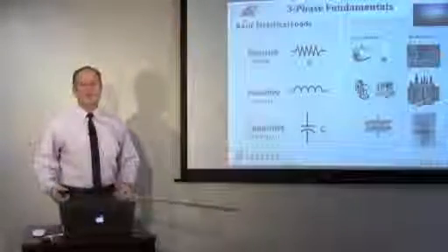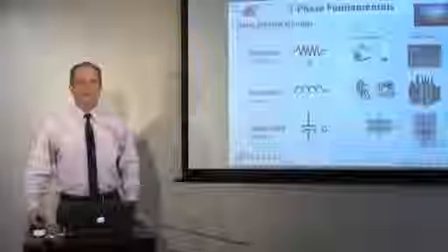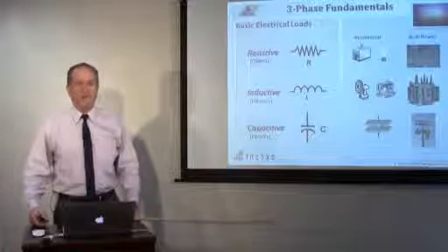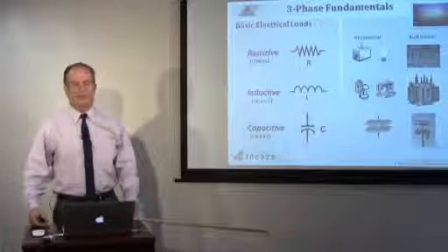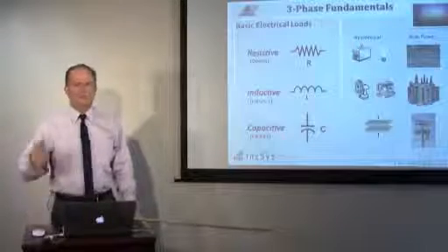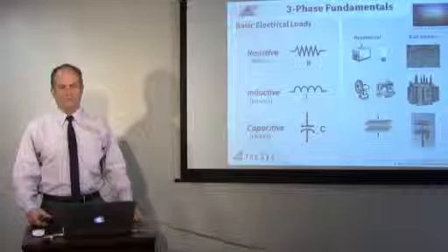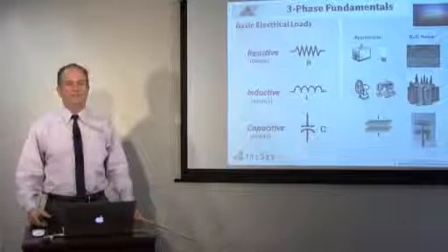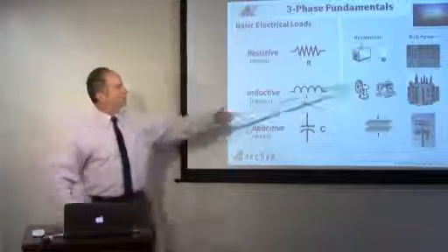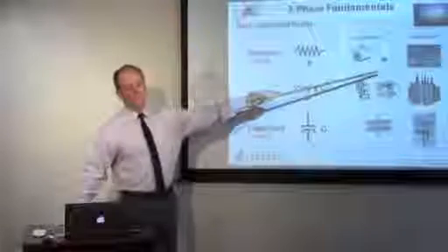Because if you take the load off the generator, it wants to spin really quickly, just like when you're driving along in your car and put it in neutral, your engine wants to really rev up. So the braking resistor keeps it from exceeding its speed so that it doesn't trip off from protective relays. So there's resistive load there. It'd be one heck of a heater if you kept it on.